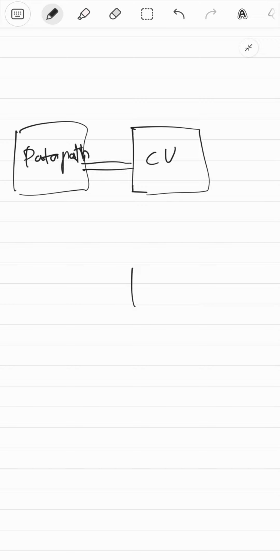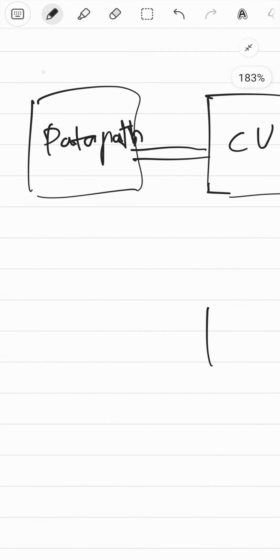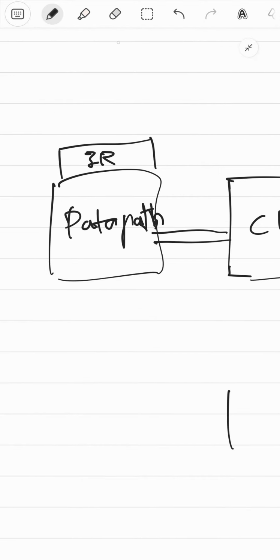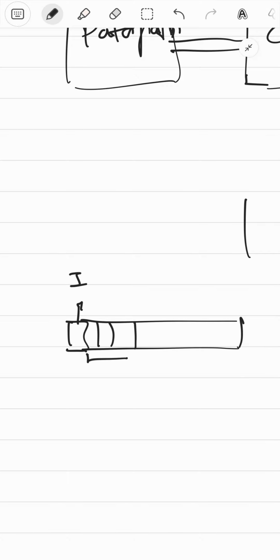One is the instructions that we read, so from the instruction register. So you have the instruction register over there somewhere, IR. So the instructions are like this. The first bit is something we call I. So yeah, it has some significance. The next 3 bits are what's considered the op code, or rather the operation basically. So I and this combined, that's actually the operation code. And then this stuff is the address in the cases that we need.